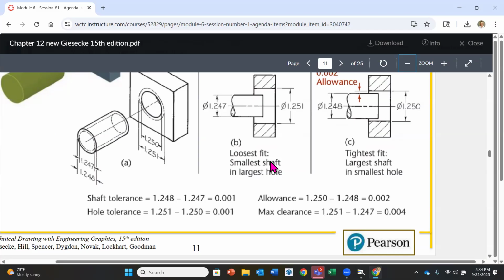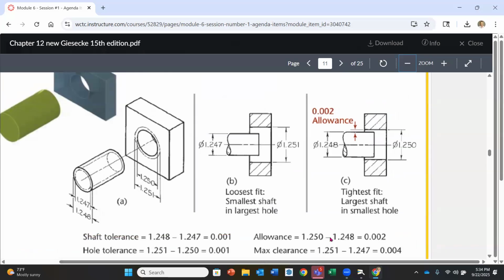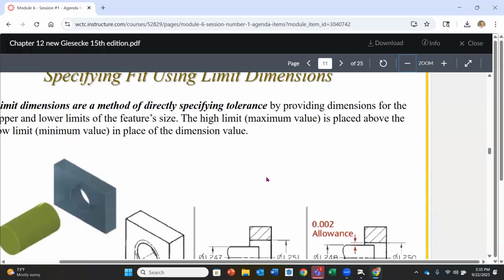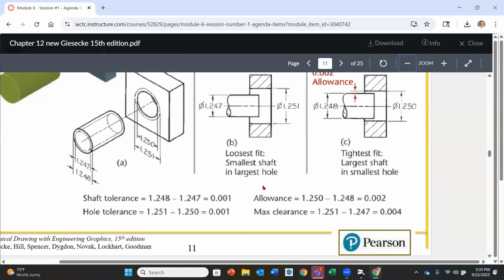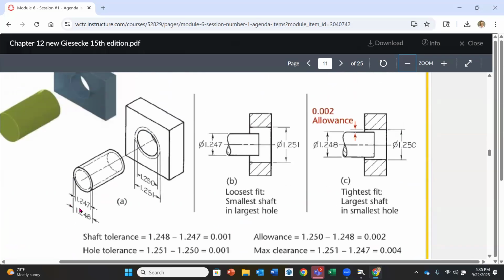In the drawings that you guys have been working on for me, you've seen limit dimensions where you're showing that high and that low value. And you've also been just having the single number that defaults to our title block. Okay. So as we look here and we look at the limits of the dimensions, you're going to notice over on the left-hand side, now, this isn't an official drawing, if you would, but they're showing us the limits. The limits is that difference between the high and the low value.